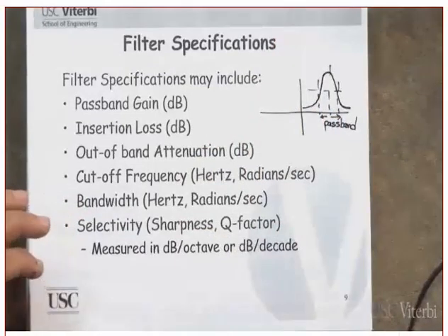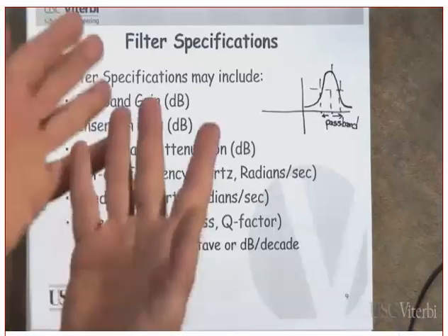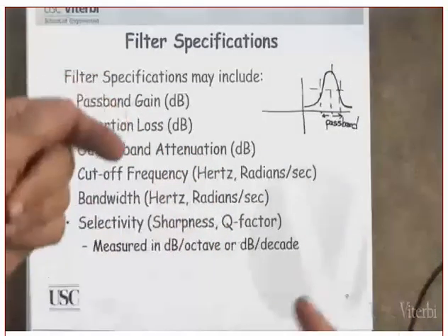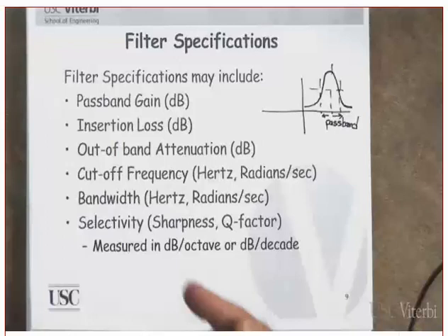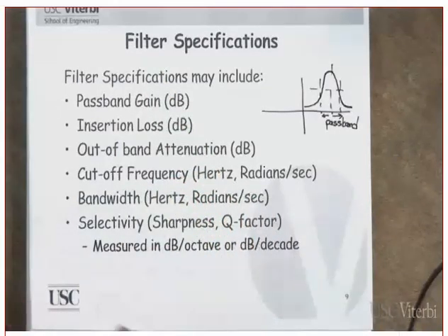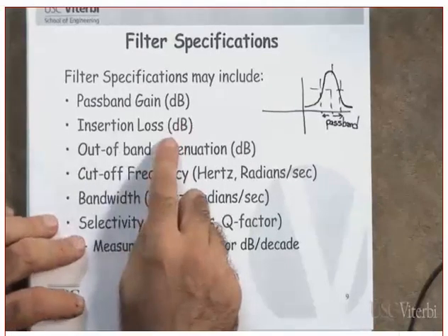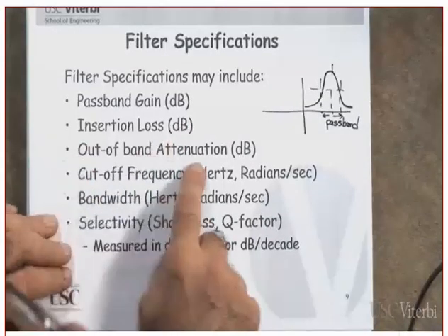Mismatches. Now, we will see shortly when we talk about matching circuits, that most of the matching circuits actually are LC circuits. LC circuits means it does not have resistances in it. But that's easier said than done. Because those inductors and capacitors already have parasitic resistances in them. Did you understand that or not? That will provide for insertion loss. And it's also in dB. Clear?